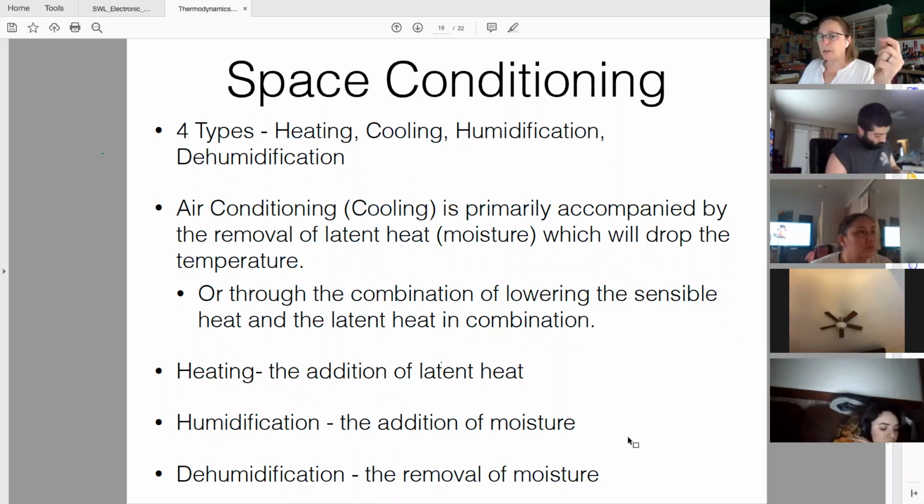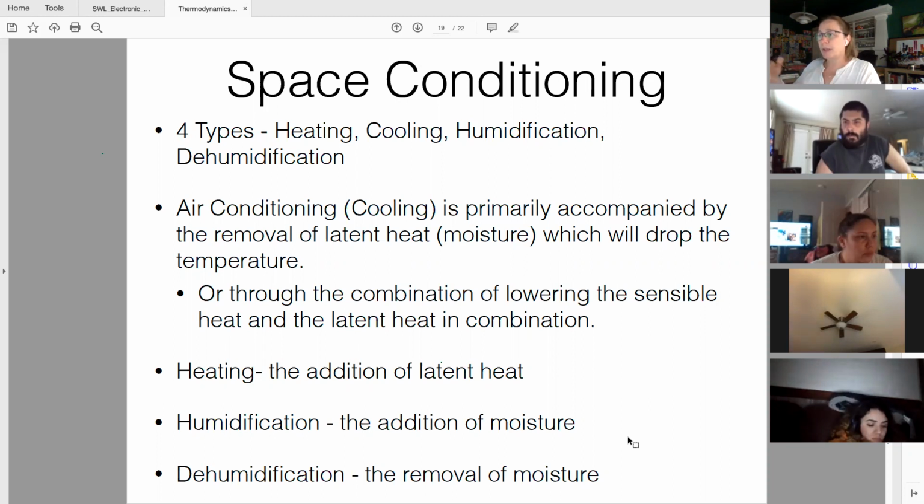There's other types of cooling methods, and there's some passive types. You can do passive cooling, where you're running cool water through a slab or another piece of mass. But all that can do is change the air temperature through conduction and convection and radiation. It cannot physically remove moisture from the air. And in fact, you don't want it to condensate on a floor if you're doing passive cooling. So that's when you have to watch your dew point to make sure that you're not creating temperatures where it's going to cause condensation on your flooring.